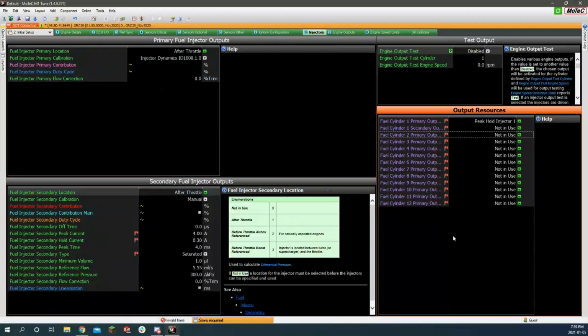Also, if you want to run 2 different types of fuel, one way to do it is to run one type of fuel to one set of injectors and another type to another set of injectors. That makes it so you can switch between fuel types instantly. You can run on your regular gasoline for normal cruising. If you floor it, it immediately starts shooting in an ethanol-based fuel or whatever to make more power.